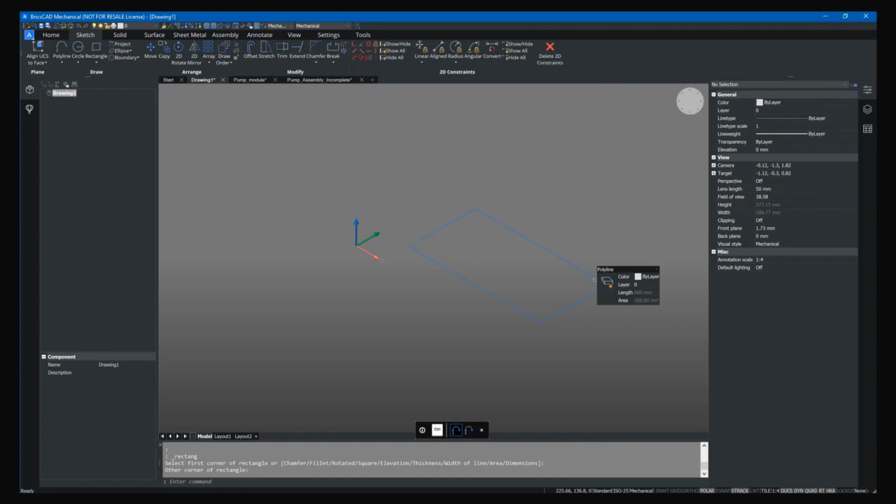And you can see if I hover over it, the quad will detect that I have selected a polyline. It will ask me and give me some different suggestions for what tools I can use. Also, if none of the tools on the top here are suited to what I want to do next, I can always go to these sub-tabs where I have a wider range of different options, for example, offset. So I can immediately get the chance to offset this rectangle just by hovering over my model.